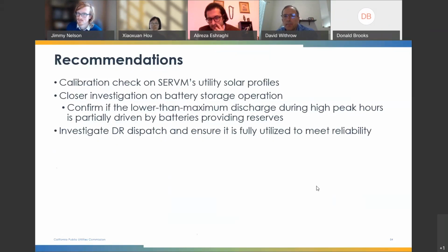Hey, this is Kevin Card. We're the SERVM vendor again with Eshraghi Consulting. So just to that last question, wanted to confirm. It's actually a weekly commitment window that we use for the optimization. So it looks over the entire week to perform the commitment. It does the dispatch on that entire week as well, but that's a preliminary based on expectation of load, wind, and solar and so forth. So it is a weekly window that we use for the commitment.